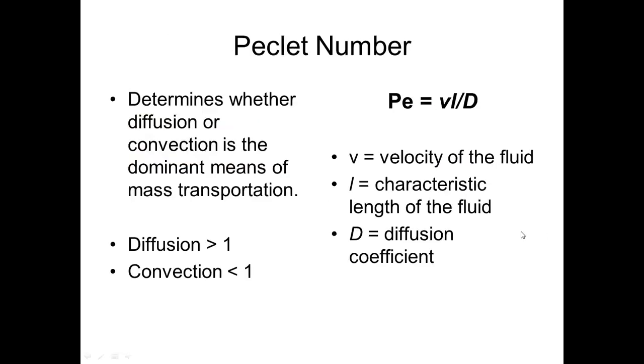We not only have that mechanical flowing or mechanical mixing of the fluid, we can have another parameter. Well, there's many parameters, probably a dozen, but a second parameter to look at is called the Péclet number. Basically, this works on the velocity of the fluid and the diffusion coefficient. The diffusion coefficient is the chemical affinity for the material to mix together. So if there's a strong, say, ionic concentration of the material, then that could elicit a fluid flow across a boundary. So we certainly have the mechanical fluid flowing that we would look at with the simple equation in microfluidics.